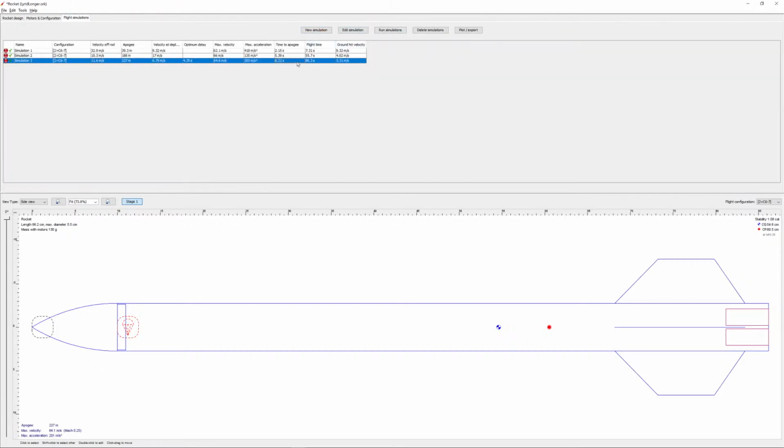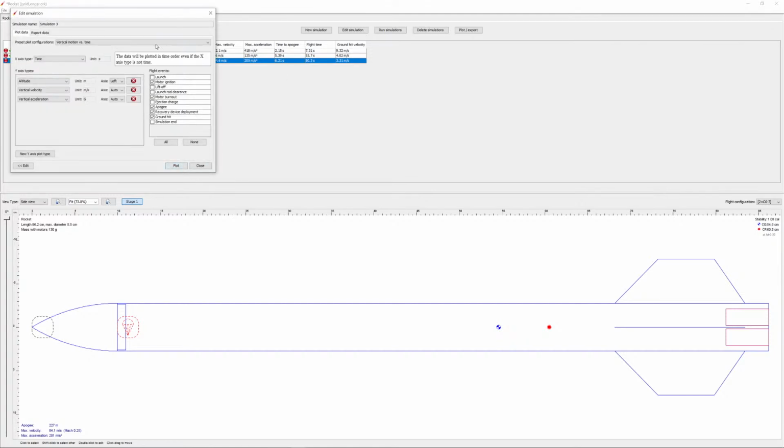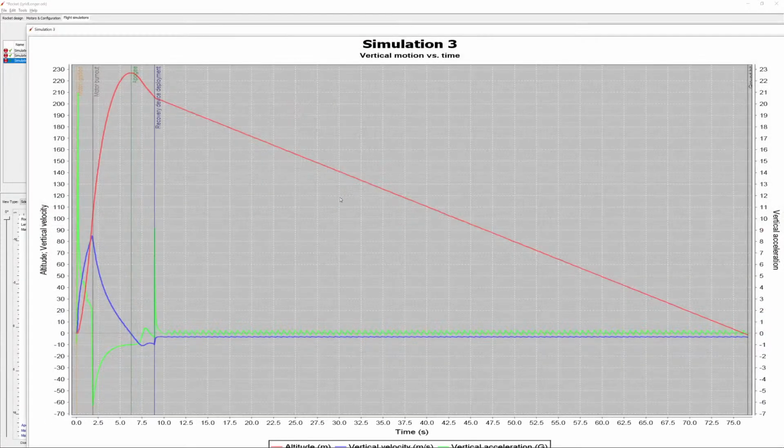And you run simulate and plot with the C6-7s, right? Yep. Plot it. You can see that you fall pretty rapidly for a good while, down to about 200 meters or so, 205, and then your parachute deploys. So that would really allow you some time for the nose cone to fall off. Hopefully we won't need that, but worst case scenario, that gives you a good time for your nose cone to fall off.